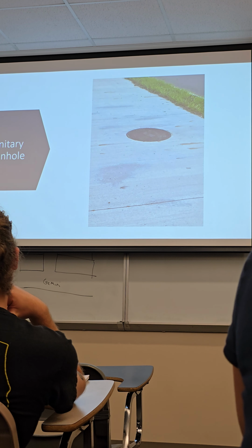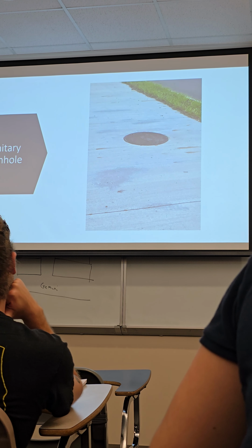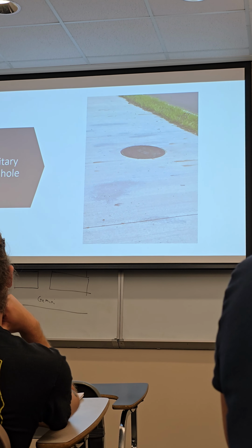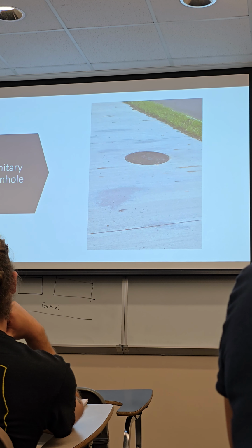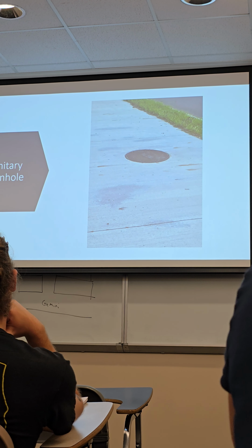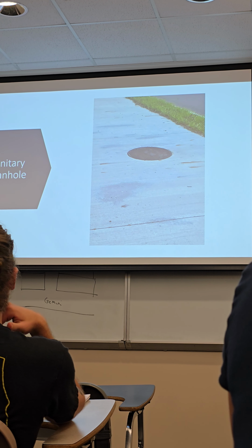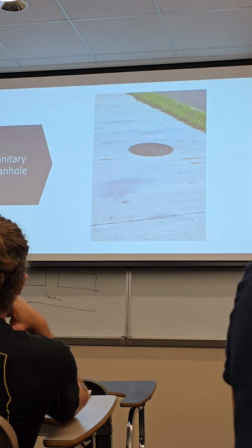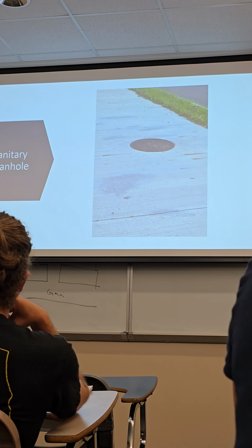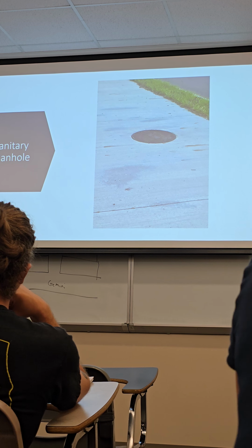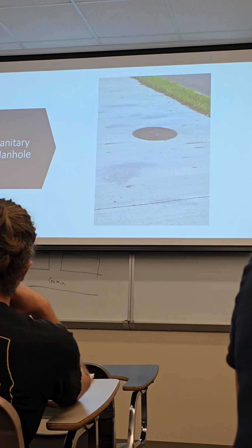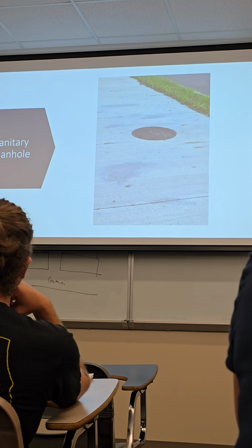But then, why would you do that? A lot of roads, and State Road 434 is like that, you'll notice that at some point the road widened, but when they built the storm sewer, it's in a certain location, and they don't want to move it. So what they'll do is build to the outside, add an inlet, and then add a manhole, and then connect it that way. So that's one reason why you might see that.